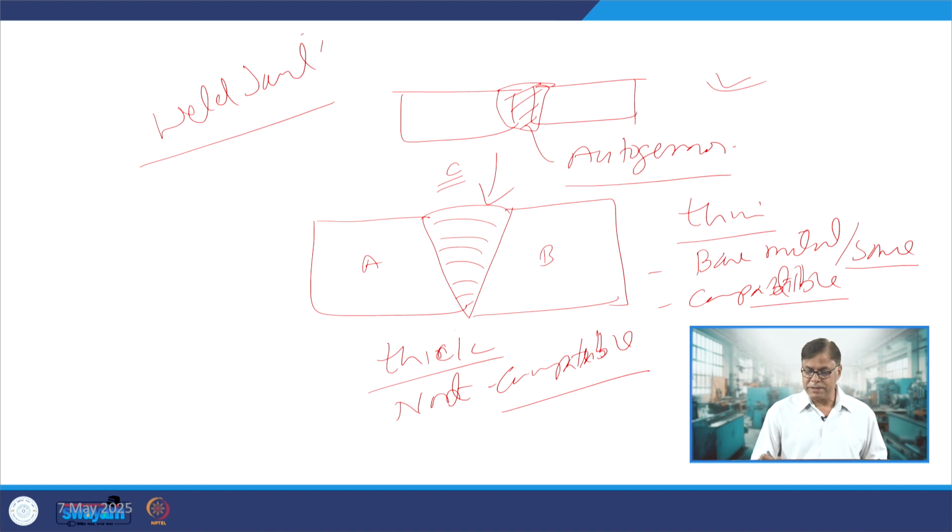So this is the case where, in autogenous welding, mostly epitaxial solidification takes place, but when a filler metal of different composition is used, then the typical nucleation and growth approach of solidification occurs for the development of the joint. This is about fusion welding.